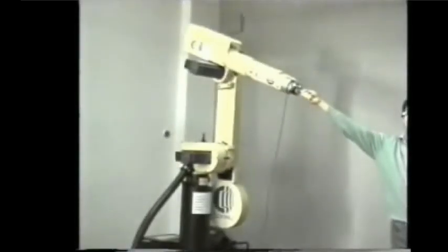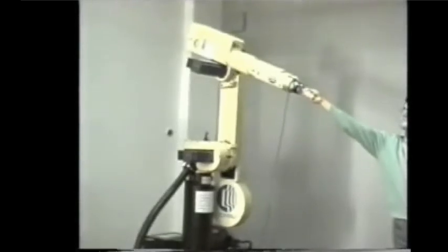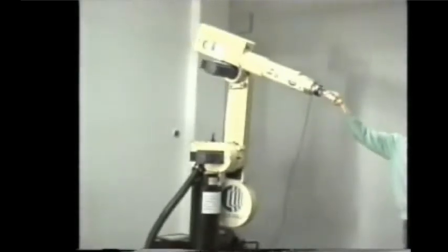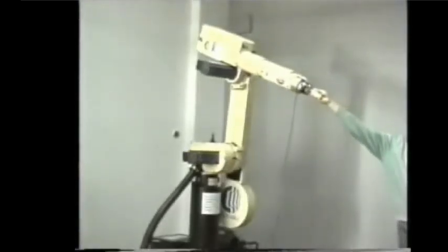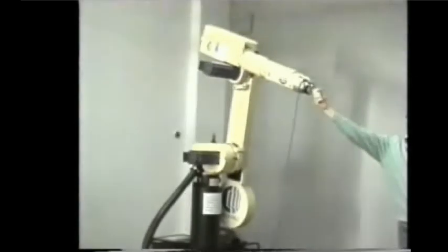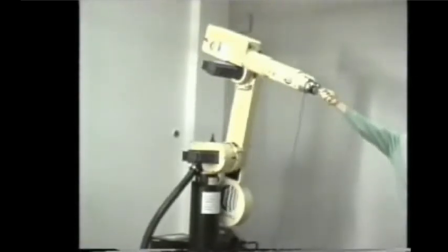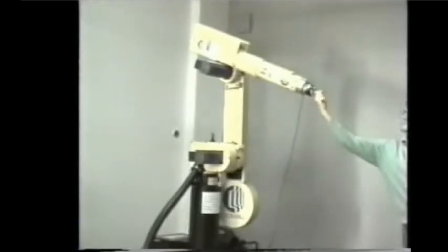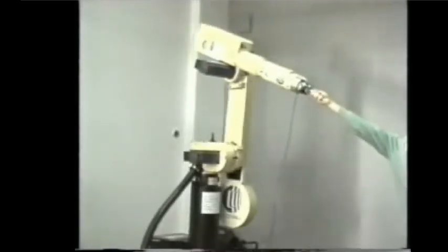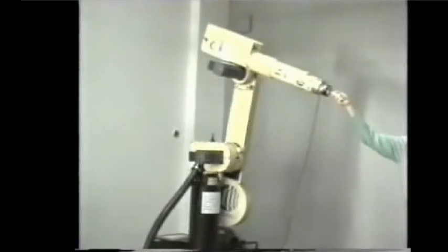you have a situation where in free space you're controlling separately a zero desired force on the horizontal plane, so the robot will follow the hand, but a very steep position control on the vertical, so that you will not be able to move the end effector up and down while you're free to move the end effector on the horizontal plane.